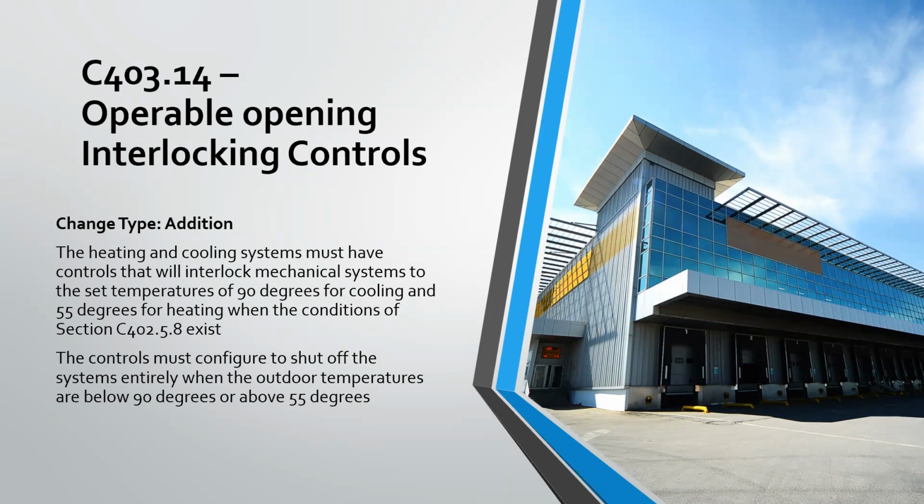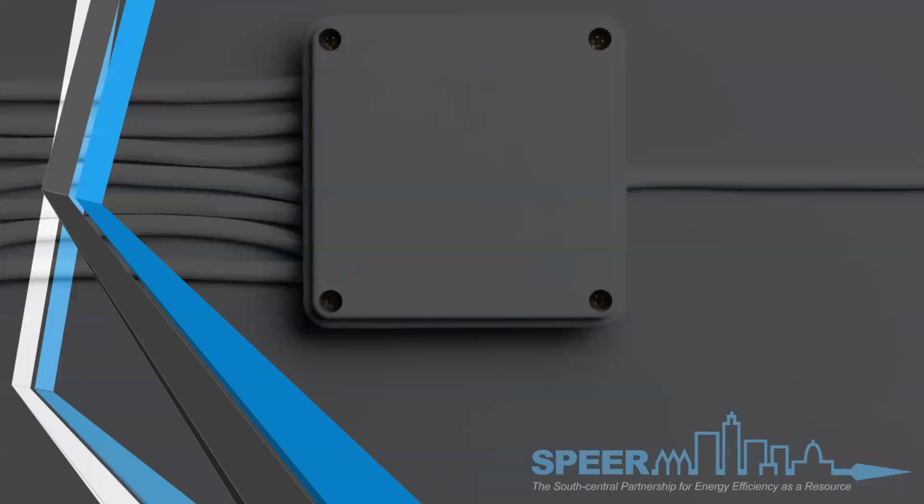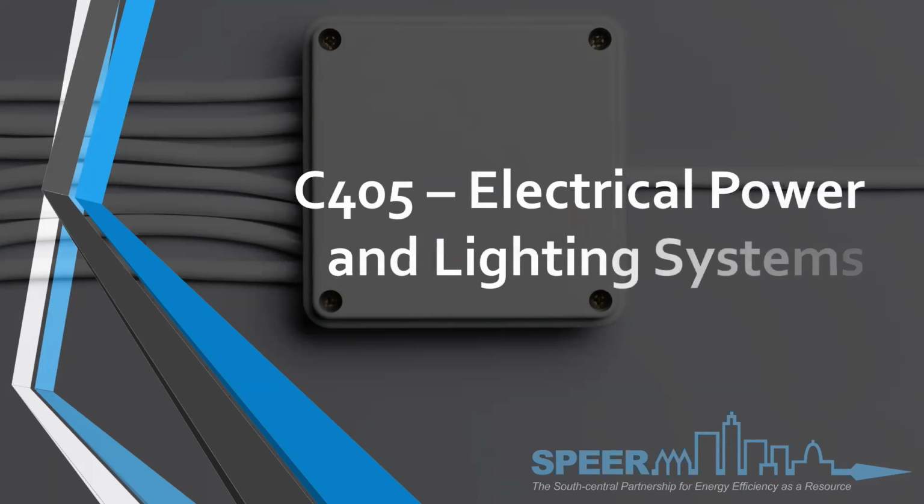So those things need to be handled for loading docks. They still are required to have either weather seals or some kind of restriction for infiltration when it's actually being used for loading. If you're looking closely at this picture, that second door there is actually left wide open. So if that door is open and it's part of the interlock, then that would actually change the settings for the thermostat or the HVAC in there, just because that door is halfway open. So you need to have those interlocking controls.